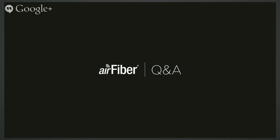We do have in the lab, and I don't want anyone to get excited about this and say, oh, Chuck said they're about to do this, because Chuck's not saying that. In the lab, we do have links that are running at 256 QAM, and we have played with 1024 QAM, even at 24 gigahertz. However, it's very difficult to build a radio in that frequency band inexpensively that's capable of repeatedly doing that. We do have some specific radios that are capable of doing that in the lab, but it's not something that we can manufacture in large quantity and control so that we can guarantee that every radio is going to operate there.